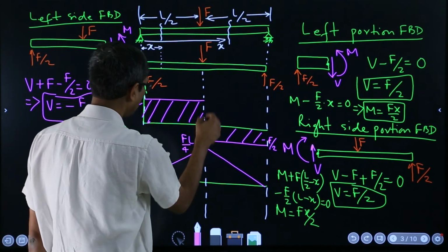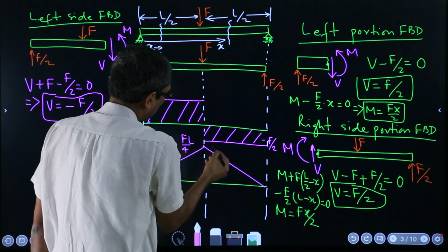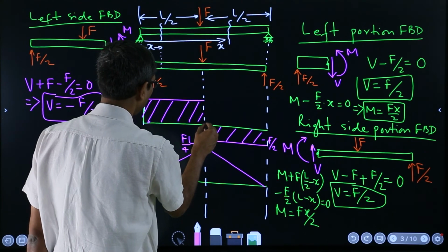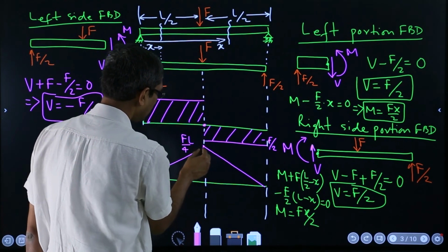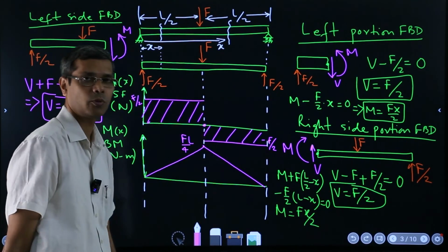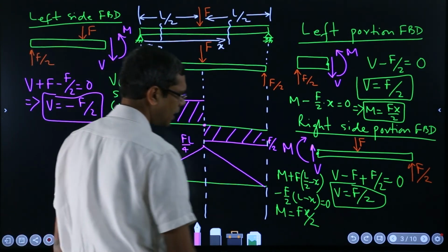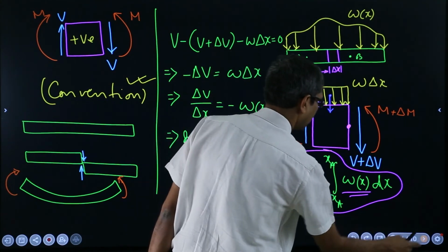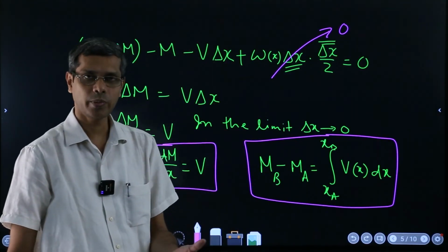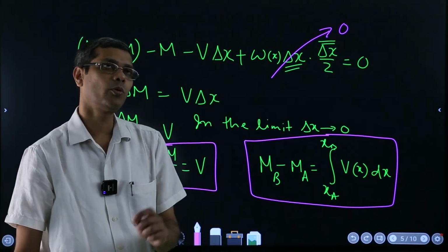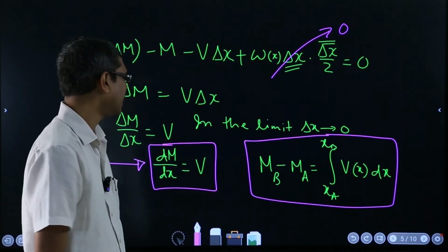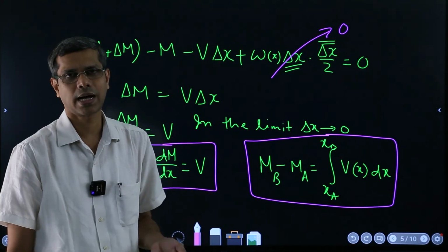Here it is crossing, though it's a jump. So the 0 point of shear force is somewhere here, and you are getting a maximum bending moment at this location, and that is the point where it's critical. The maximum moment corresponds to the maximum normal stress, the bending stress, and the failure possibility is higher there.